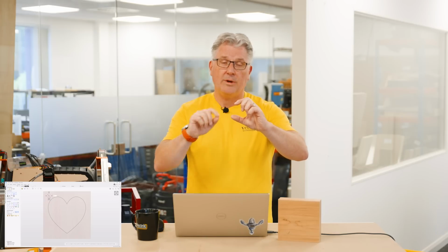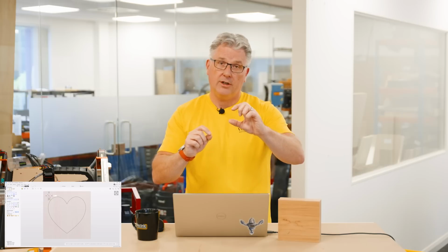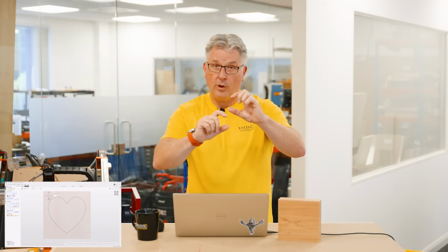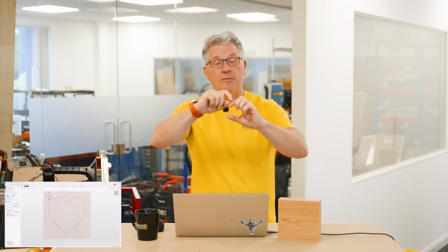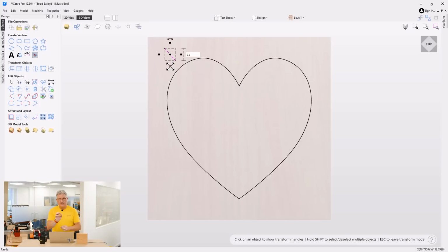I want to make sure that the Moulding Toolpath part of this is only 10 millimeters tall. I can add material below it if I'd like to raise it up, and I can remove material from above it if I need to. So I have a lot of control over how thick this piece of molding is going to be. So that 10 millimeters is going to be important, and also this 8.89 is going to be important a little later on when I talk about how I use this in the project.